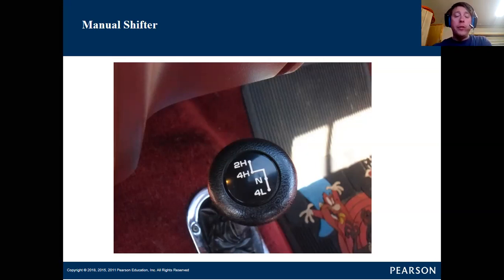All automatic transmissions need to have the engine running in order for the automatic transmission's fluid pump to spin. And so you cannot tow an automatic transmission vehicle with its drive wheels on the ground and just simply pop it in neutral. You have to disengage the transmission entirely if you're going to have its drive wheels on the ground. Otherwise, it won't lubricate. So it's a trick that people do. If you have a vehicle with a transfer case that you can pop into neutral, a lot of times you can get away with flat towing and not have to worry about it.